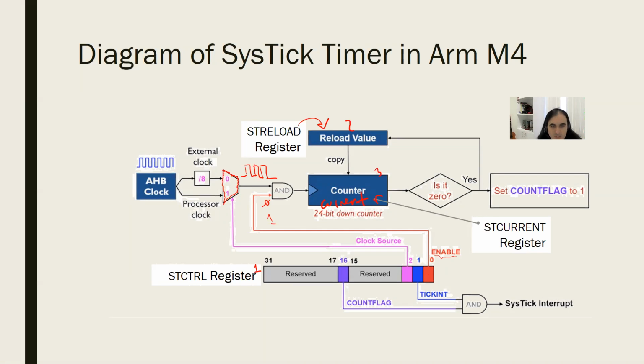Do you remember this component from logic design? What was it called? It's called a MUX. Multiplexer, exactly. A multiplexer is a device which makes a clever selection. If this is the control bit, if the control bit is 0, this input is provided through as the output. If this bit is 1, this input is provided through as the output.